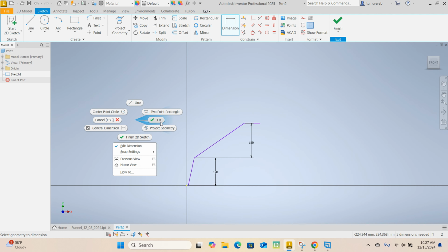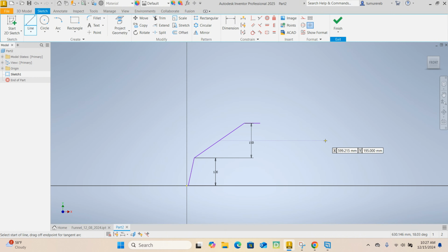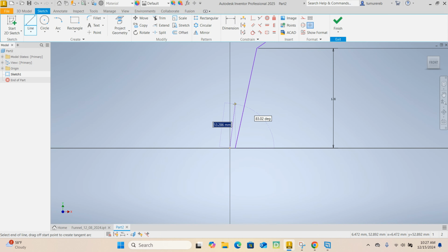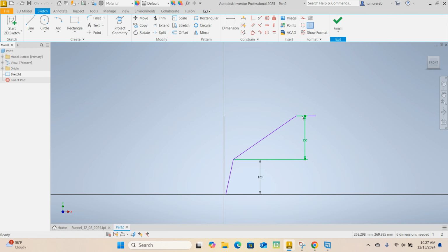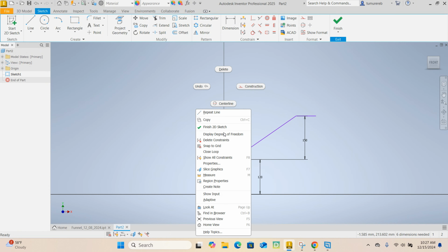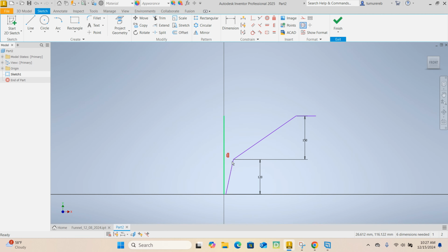All right, let's go ahead and draw another line. Draw a line from here to about there. I'm going to use a reference line. If you move your mouse here, but don't click, you get this reference dotted line. Then click, and let's cancel that. So we got a line, and it's about this height. Select this line and make it a center line.